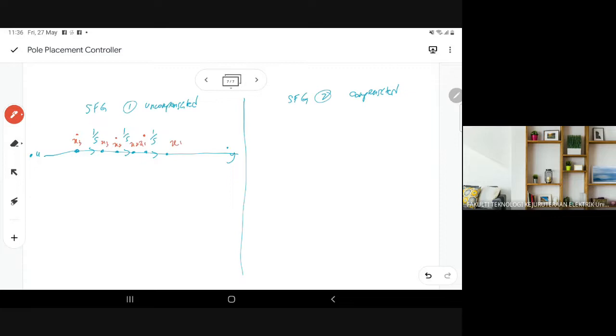Okay. After that, according to this, here will be 1, 1. And after that, X3 dot is actually coming from negative 5 X3 and negative 4 X2, and plus 1 multiplied with U. And then for the output Y, we have 100 X1 plus 20 X2. Okay, this is the original system now.